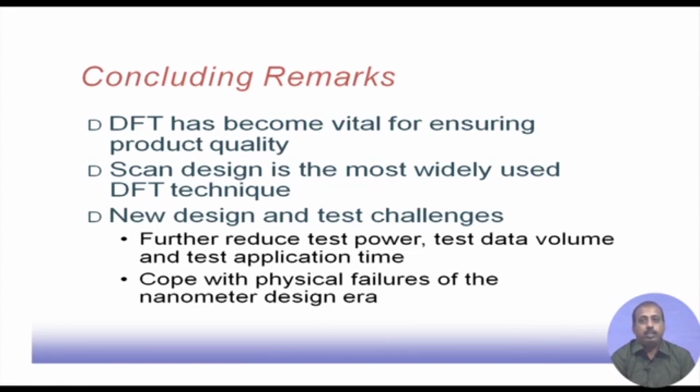So, what is happening is that as the circuit is becoming more complex, the test data volume is also increasing significantly. So, storing all those test data onto ATE is a challenge. So, we can try to do something by means of something known as test compression and all that, so that this data volume is less, and application time also needs to be reduced. Application time can be reduced by using many techniques, like one is definitely reducing the number of test patterns, another is transferring the test patterns faster from ATE to the device.